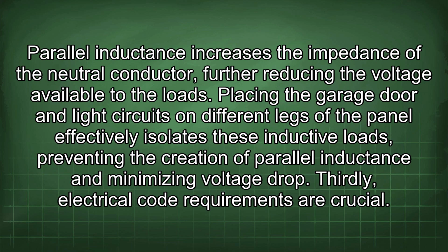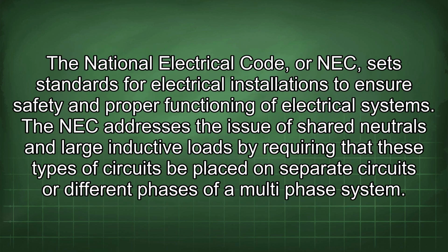Thirdly, electrical code requirements are crucial. The National Electrical Code, or NEC, sets standards for electrical installations to ensure safety and proper functioning of electrical systems. The NEC addresses the issue of shared neutrals and large inductive loads by requiring that these types of circuits be placed on separate circuits or different phases of a multi-phase system.